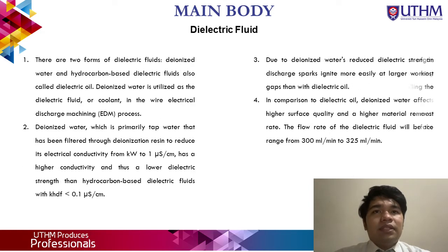And for the last part is the dielectric fluid. For this project, we used deionized water, which is primarily tap water that has been filtered through deionization resin to reduce its electrical conductivity.